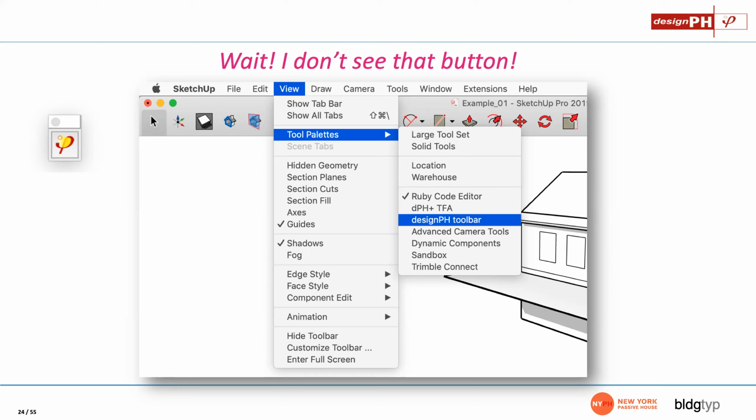Well, technically, I don't know how to answer this. Technically, no. Psi-values are not a creation of Passive House. If you go to your ASHRAE Fundamentals Handbook, or if you go to the ISO modeling procedures, they outline how to do psi-value calculations and how to quantify them. Psi-values were not something that Passive House invented.